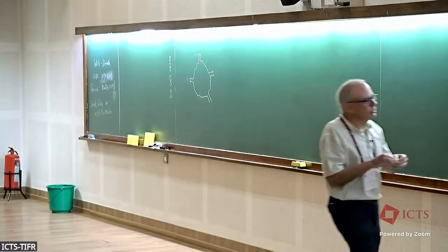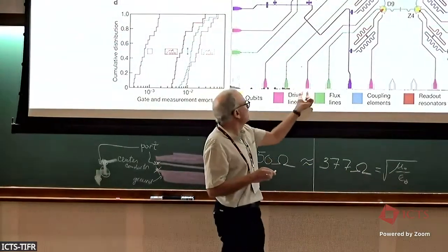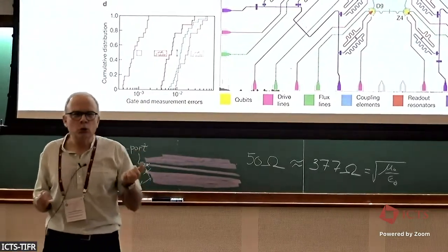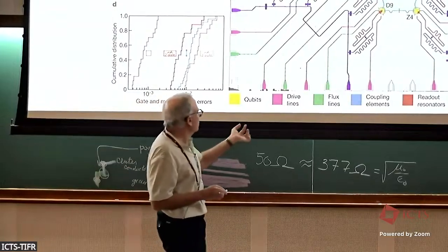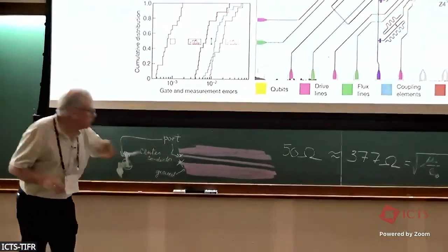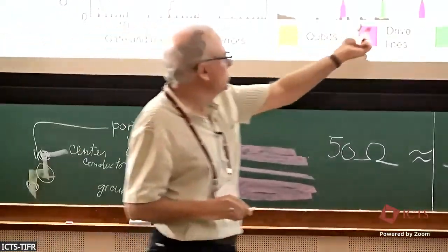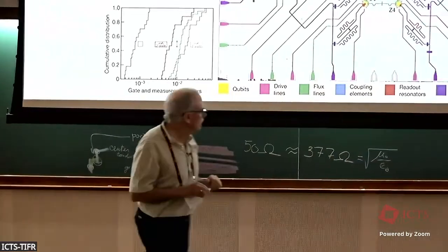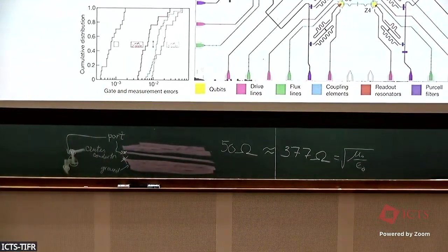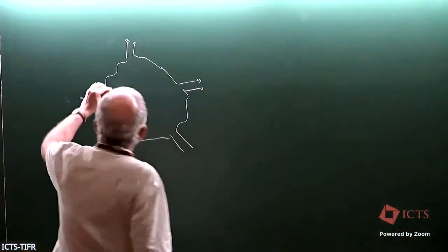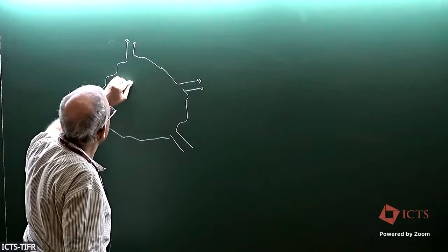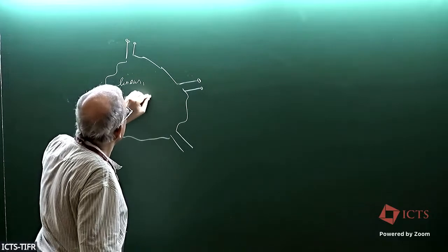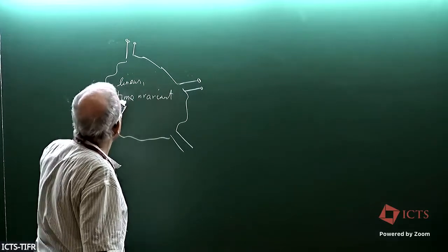So there's a port, and there are ports all along here. In many languages it's called two poles, Zweipol in German, just to emphasize that it involves a pair of contacts, so to speak. So here, here, here, and then all 17 of these Josephson junctions get their own assignment as a port, and then the rest is a linear time invariant network.